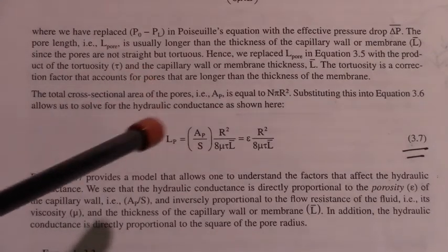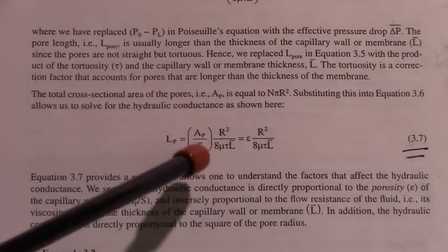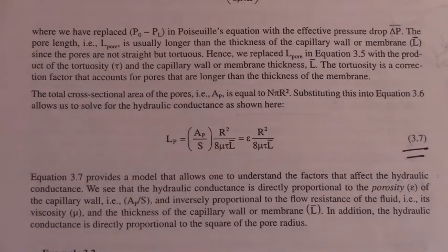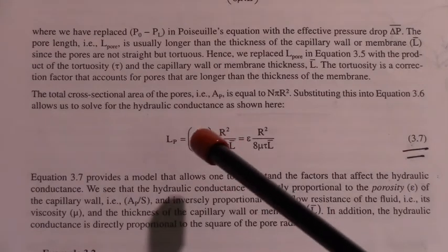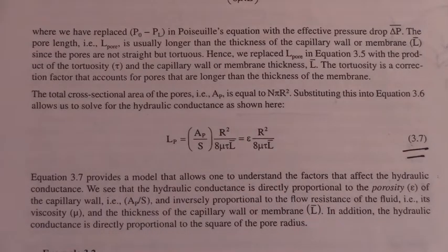This would be the surface area of the openings divided by the total membrane surface area. That ratio is called the porosity of the membrane. When you buy or make membranes, you make them with a specific porosity, epsilon. That becomes a degree of freedom, part of your design process. You're saying, hey, I want my membranes to have a porosity of 40% or 25%.